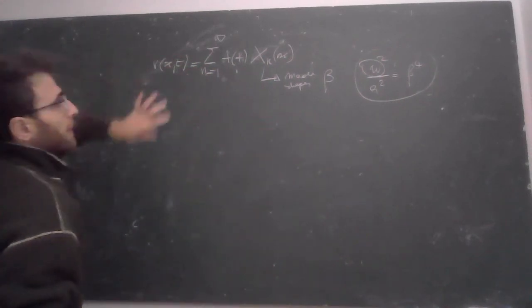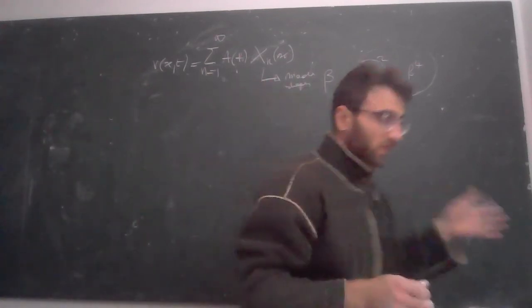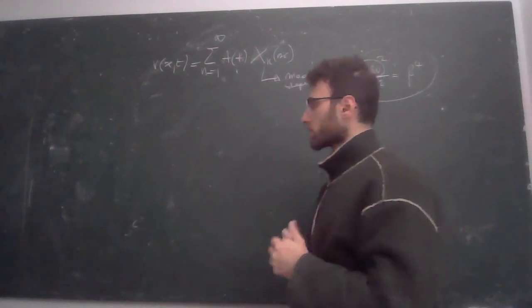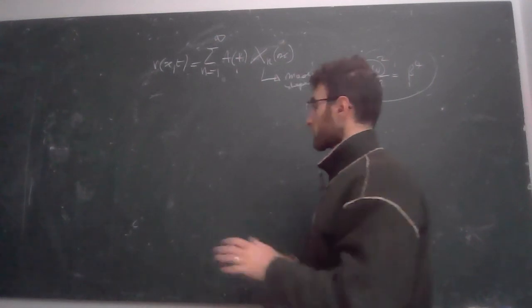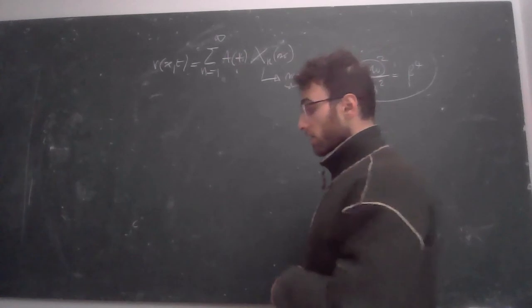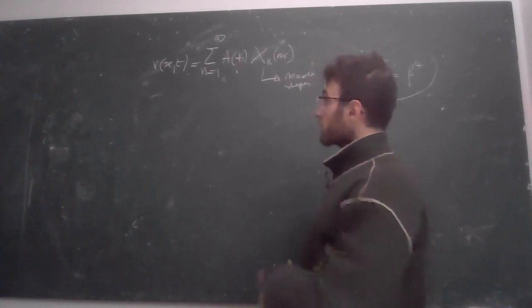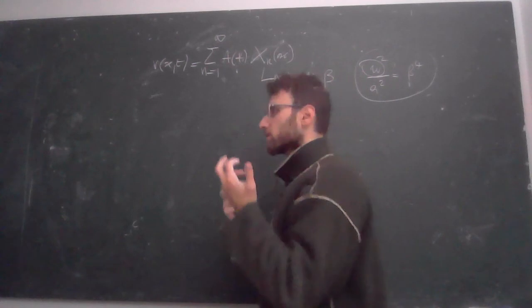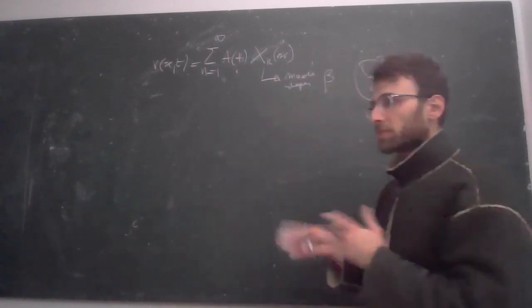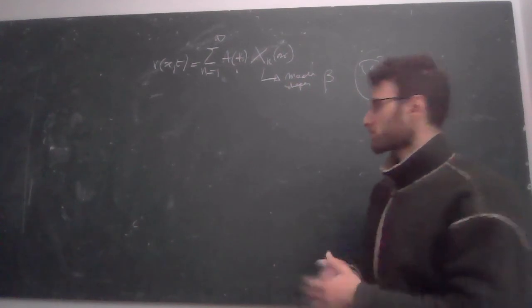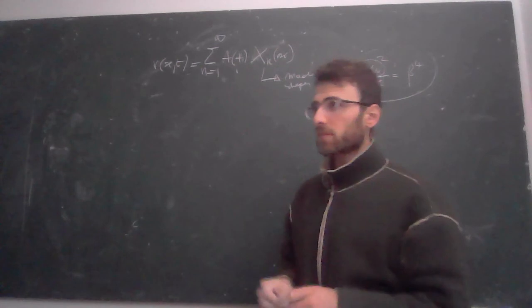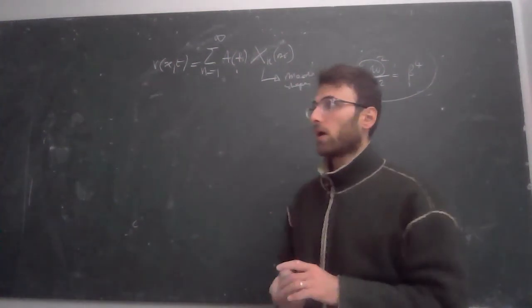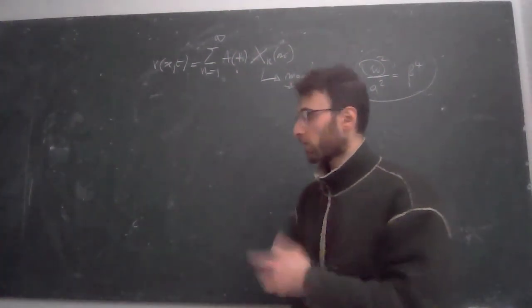Right. You studied before in the other part of the course that mode shapes are orthogonal between each other with respect to the mass or stiffness matrices. What we are considering now are these mode shapes which are no longer vectors but functions, so we call them eigenfunctions. Are these eigenfunctions orthogonal between each other? We will try to demonstrate that when we have homogeneous boundary conditions, we have orthogonal mode shapes.